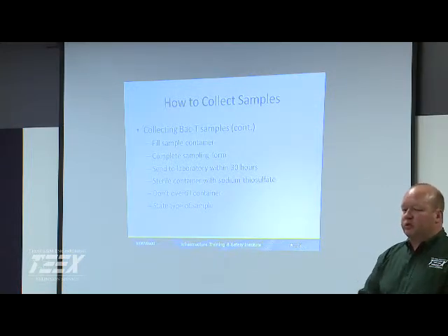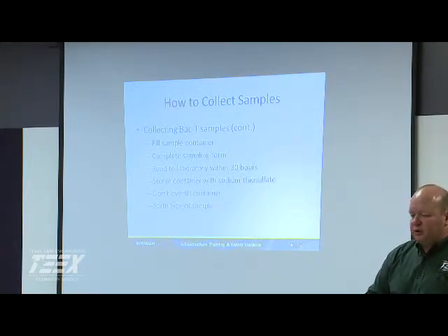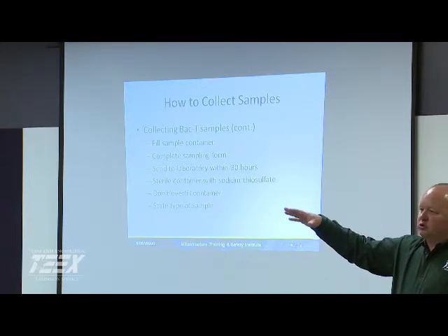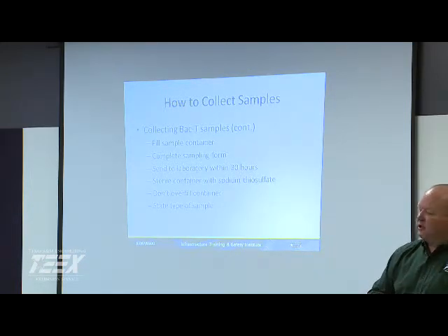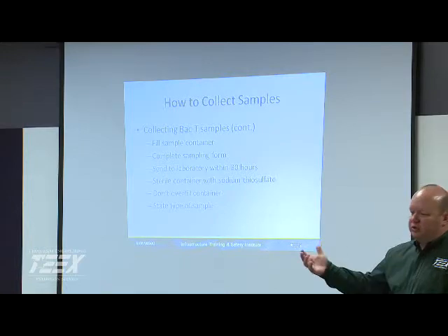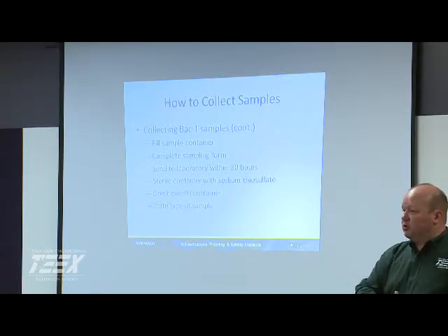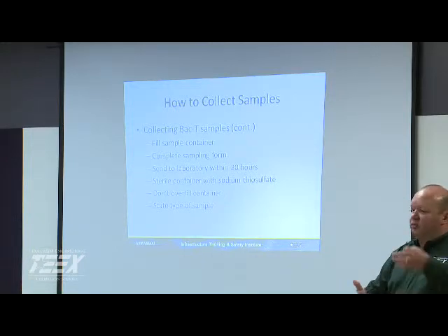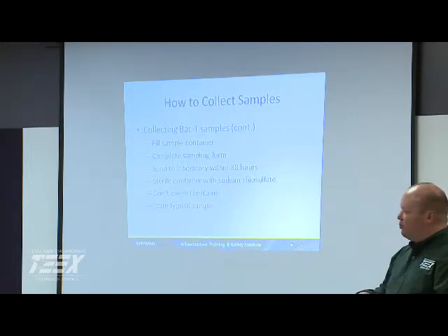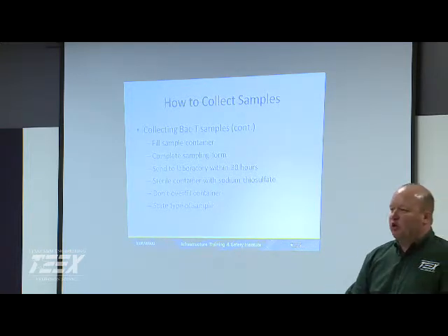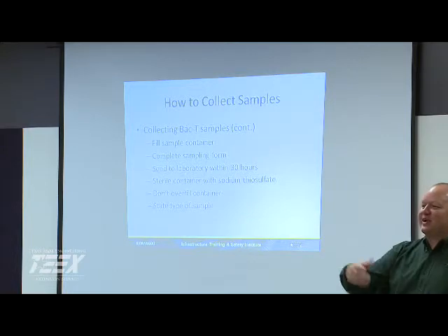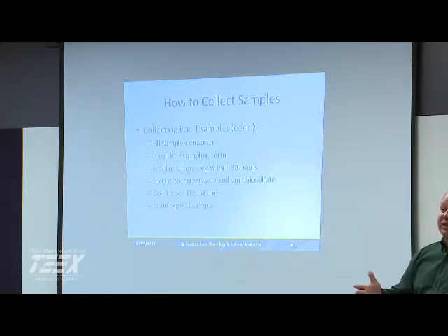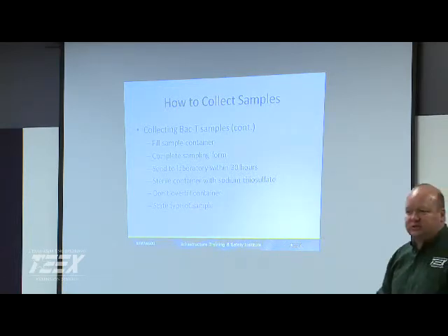Interesting. Yeah, we were really trying to push our distribution system, and it's a huge one, especially during the summer, a lot of main breaks and stuff. We were trying to push them to be more responsible on sampling after repairs, because it's all about the numbers, how fast can you get to the next job. And then they'd bring in the samples in an empty Coke bottle or something like that, or if they actually did pull it in a proper bottle, it had been sitting on the dash for 2 days.